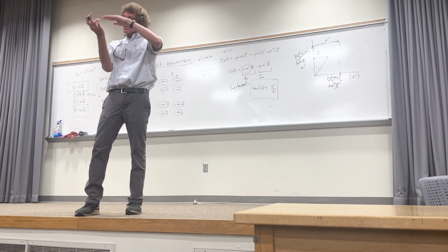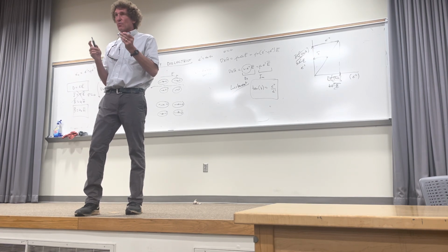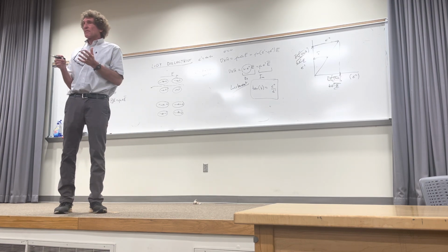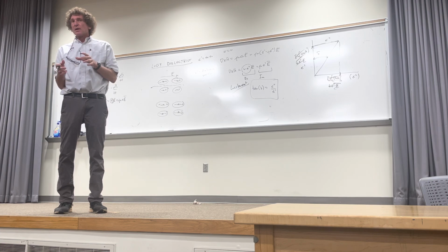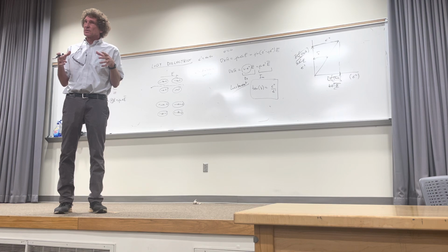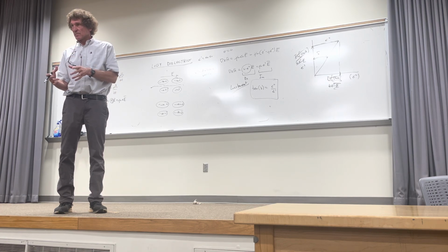Well, the material in between the upper and lower copper pieces is a dielectric. You can get really expensive materials that are very low loss. They're called Duroid board. They're about $100 a square foot. Or you can get much cheaper stuff for lower frequencies, basically for mounting components and stuff like this. Do you know what FR4 board is, that green board? Y'all know what I'm talking about? Some of you do. All right. The costs vary orders and orders of magnitude for these materials. And the lower the loss, the more expensive the material.